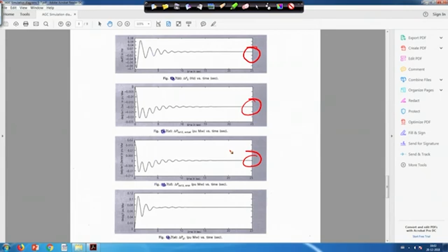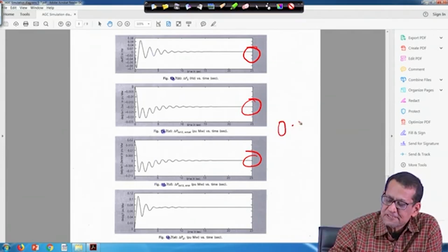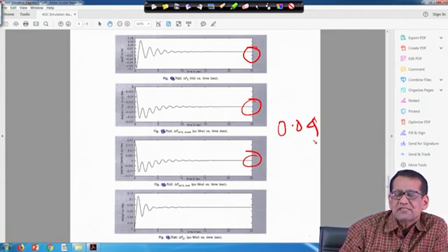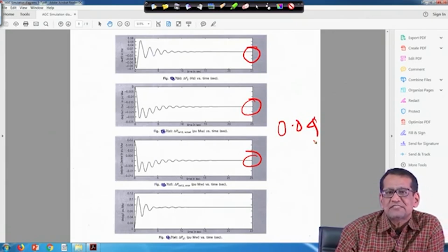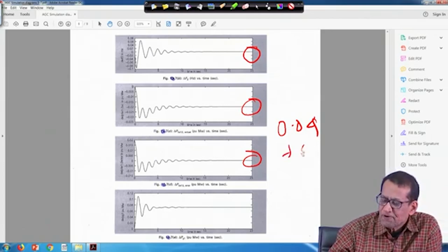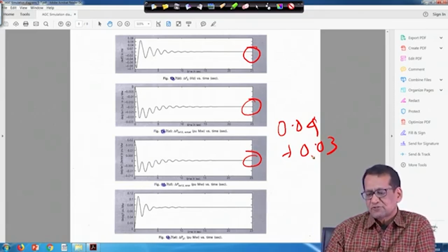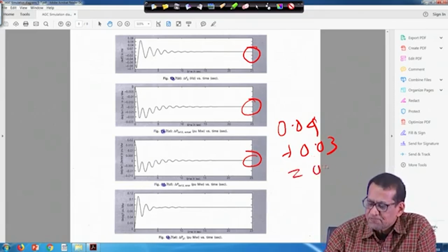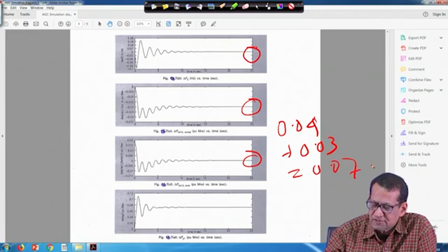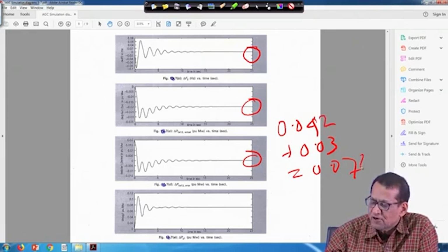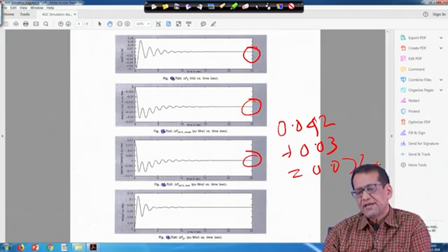But as I told you, for the case 2 it was 0.04, right, plus the AC participation factor for GENCO 1 in area 1 was 0.75. So, plus 0.03 will be added, because 0.04 into 0.75. So, total will be 0.042 plus 0.03, so 0.072, right.